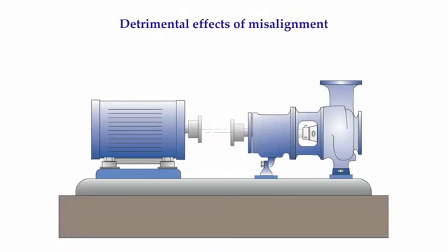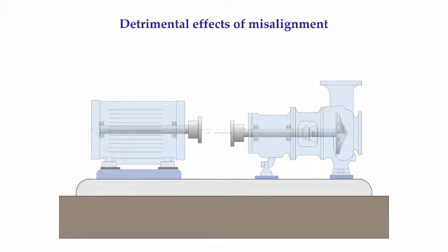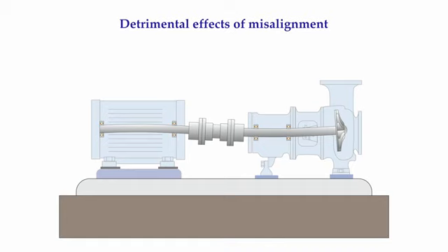If we were trying to align a motor and pump and had, let's say, a ½ inch of misalignment between the two shafts, and installed the coupling, if the machine cases were transparent and we could see the shafts inside the machines, we would observe the shafts elastically bending in an S-shaped curve.